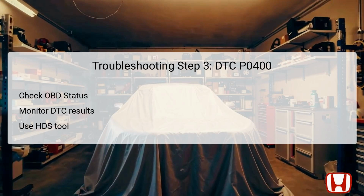At this stage, utilizing the Honda Diagnostic System (HDS) tool is essential to monitor the onboard diagnostics (OBD) status for DTC P0400. This tool provides invaluable data, confirming whether the vehicle system has detected a failure or if it remains operational. If the HDS indicates a failed status, it would confirm the presence of an issue, prompting the technician to proceed with the replacement of the EGR valve.